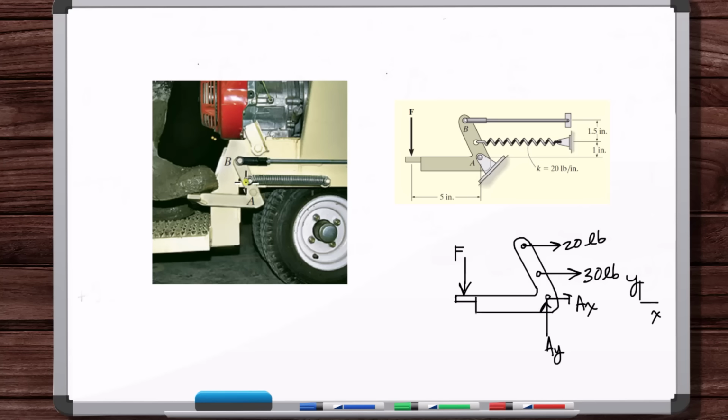But just note, we're going to talk about the different kinds of connections in a second. Ideally, like the nominal case, if you have a pin connection, even the natural friction in the pin should be negligible compared to the forces, to where there is no couple moment here. It's purely preventing translation. If you've got such a rusted connection, well, you should go fix the connection. A proper pin connection doesn't support any significant moment. Okay, so there you go. There's an example of a free body diagram.